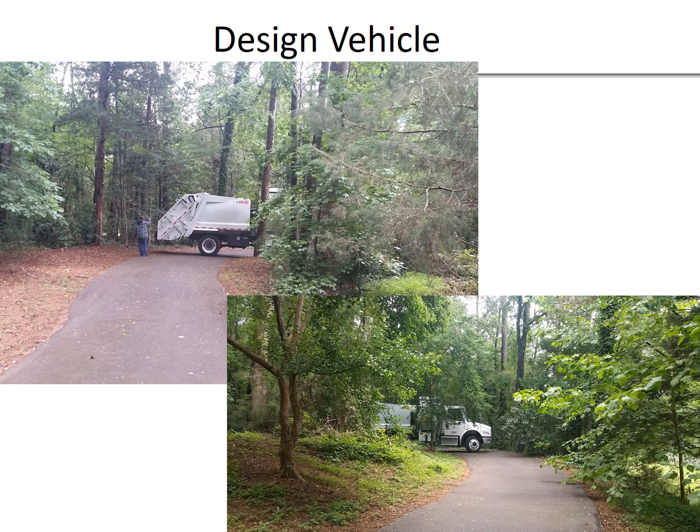They had to reposition themselves several times to try to make it down this greenway path, or maybe even make minor encroachment into side streets. A condition that uses the control vehicle concept arises when you have these large vehicles turning at intersections with low opposing traffic volumes. So a moving van in a residential neighborhood or a once per week delivery at a business, those are conditions where you may say, okay, we're not going to fully design our roadway to handle this on a normal basis, but we're going to want to consider it for infrequent uses.